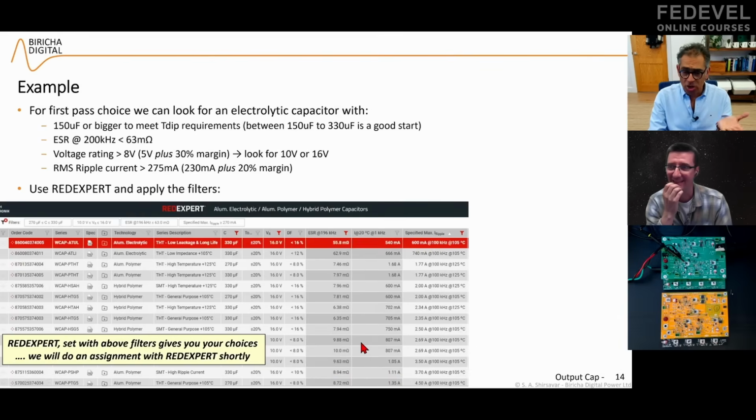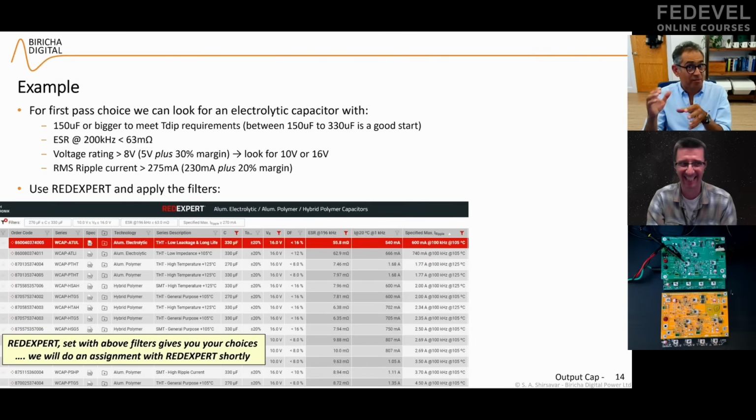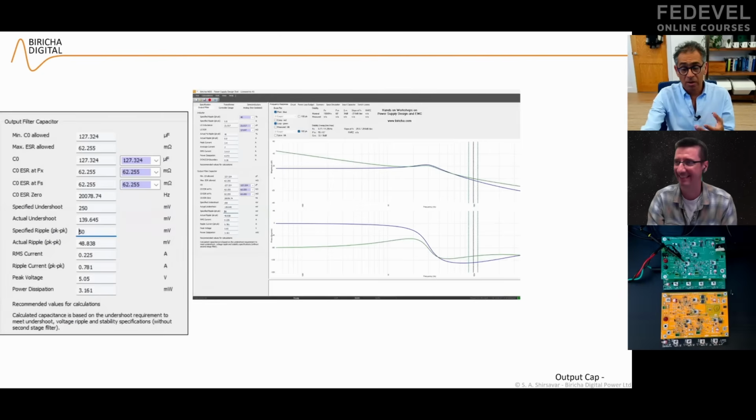That's it, actually. We showed how you select the electrolytic capacitor based on the ESR. Then we kind of went off track a little bit and we talked about ceramics and why you have to put an extra margin on the voltage because of DC bias loss. So really, you've seen all of these equations.